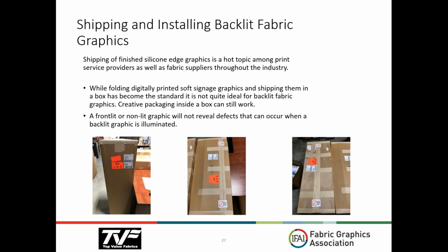Climate control is important. You want to make sure that if you're using a coated backlit fabric, that it's not too cold, it's not too hot. We have had customers who basically stored fabrics in containers out in the parking lot when it was below zero, and then try to print it. And what you'll see is fracturing actually in the coating that can occur. So you want to make sure that these fabrics are climate controlled both before printing, during printing, and after printing.